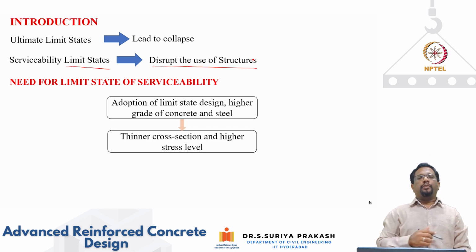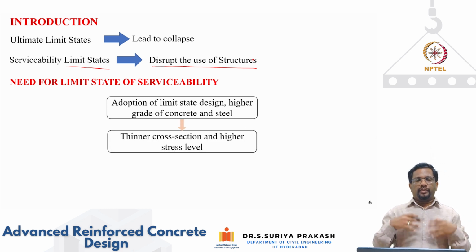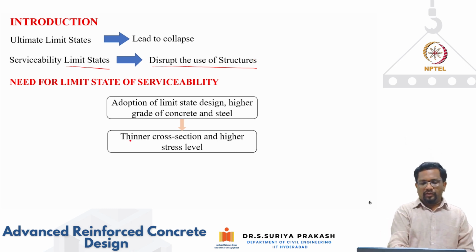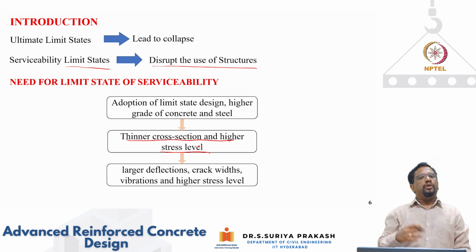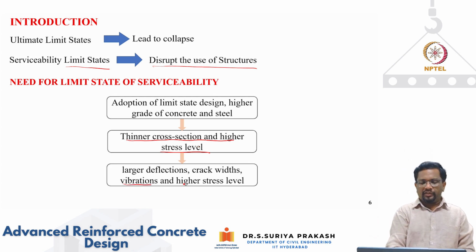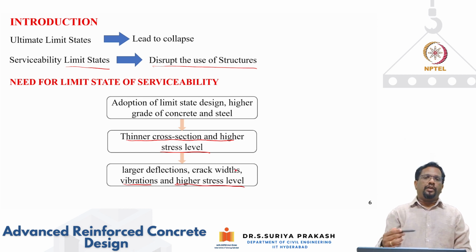Because of the adoption of this limit state design approach, where we are designing for nonlinear stress-strain curve behavior, we end up with more efficient cross sections, or in other words, thinner cross sections, and we are also allowing higher stress levels in the material. Because of that, if you're not careful in your design, you can have larger deflections, crack widths can be higher, and you may also have vibrations, and the stress level in the steel may become higher.